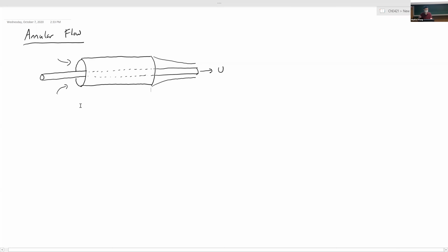And then as you pull it out, that polymer dries or solidifies on the surface of this material. Okay. And what we're going to try and figure out first is the velocity profiles inside the larger cylinder, in between the larger cylinder and the smaller cylinder. But you can imagine that this could be useful for understanding how much fluid, how much polymer or plastic, actually gets on the wire, depending on how fast you pull it, and the dimensions of the system and stuff like that, right?